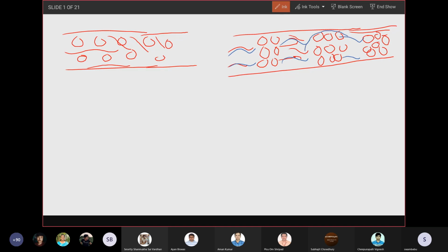Since the solids are flowing like bunches, attrition between the particles will be very minimal, because particles will not hit each other. One big agglomerate of solid is just moving instead of the individual fine particles. So the advantage is that you can minimize attrition, but you need high pressure to push the solid, to transport the solid particles.